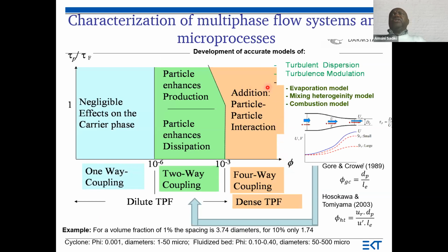And here we can now introduce some new aspects. As we explained before, in addition to the dispersion process, here we need also the modulation process. This means the variation of the turbulence of the liquid phase, of the carrier phase, due to the presence of particles or droplets.